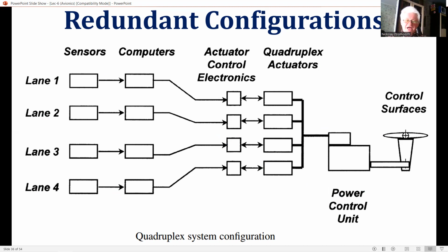The integrity of the electrical power supplies and the hydraulic power supplies is absolutely vital, and adequate redundancy must be provided so that the system can survive failures in both the electrical and hydraulic power supply. In fact, the starting point in the design of a fly-by-wire system is the safety, integrity and redundancy levels required of the electrical and hydraulic power supply systems, as their integrity dominates the overall FBW system integrity.